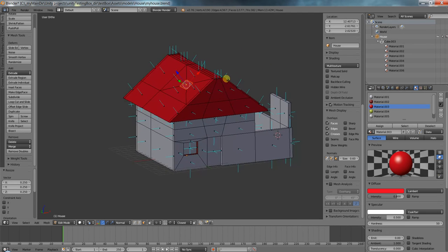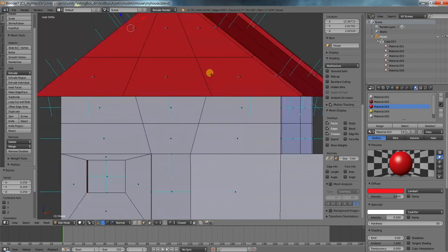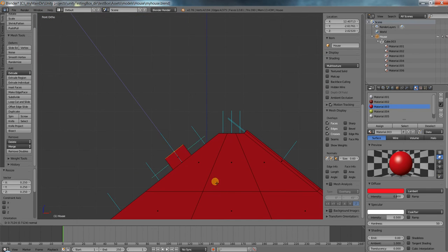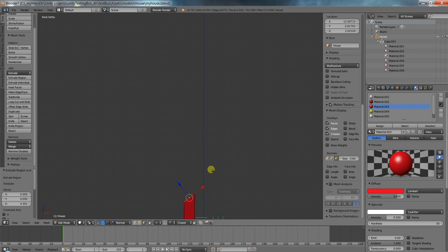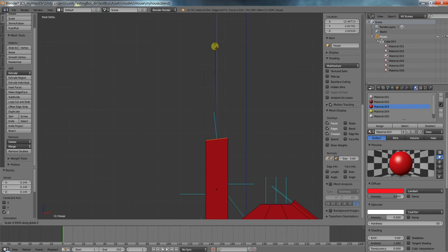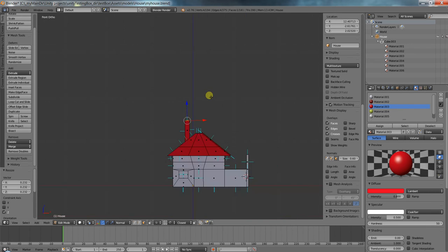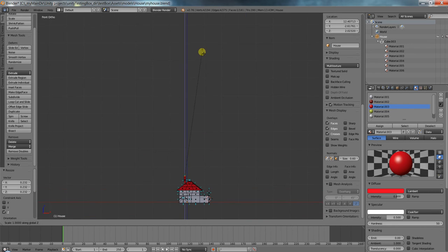But now if I were to extrude on the z-axis, fine, it's going up and down on the z-axis, right? But the top has kind of kept its slant. So we're going to use scale again. If I scale this surface on the z-axis, SZ, it'll flatten out. And it's the same trick. You move far out and you scale Z, and you don't pass that point.